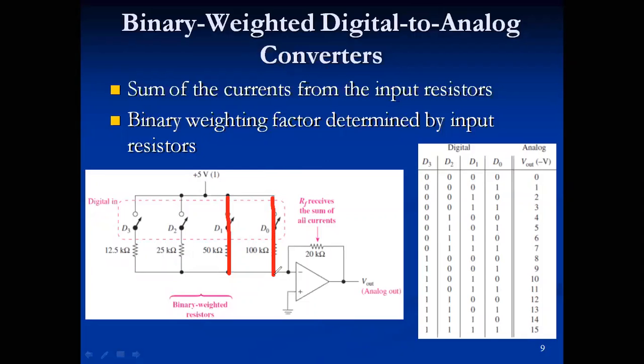All right, and now you're going to see that this is a parallel connection. And I don't know if you remember your parallel theory, but what we have is a total resistance of... What we do is we take 100 times 50, and then we divide by the sum of 150.